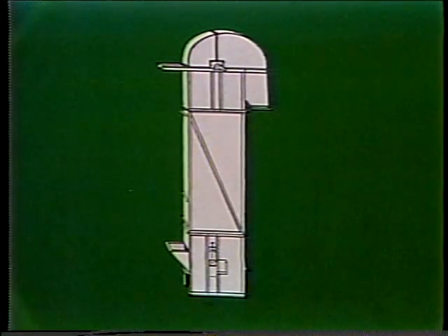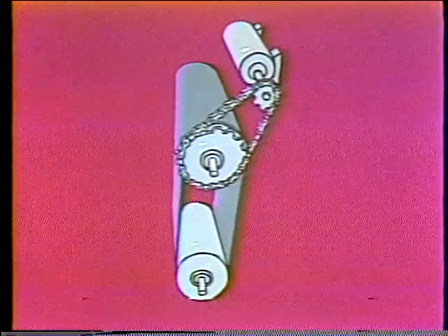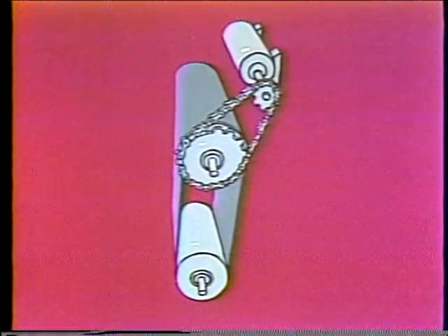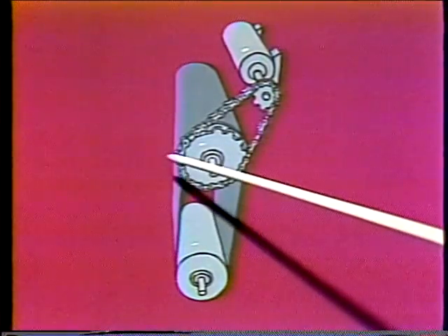These two pulleys have shafts and are mounted on bearings much like a belt conveyor. In fact, an elevator can be termed a flat belt conveyor, which has been turned up on its end and has buckets attached to the belt so the material won't fall off the belt. The drive is very similar to the types used on regular belt conveyors and is normally mounted on the top.